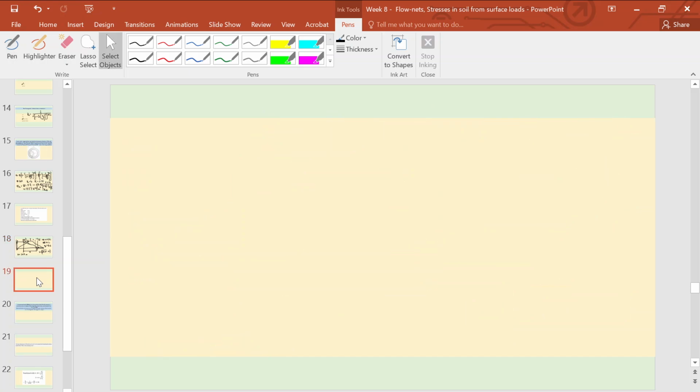So now I'll write the formula for D, which will be equal to 0.3 L, the first part on the left side upstream, plus the horizontal part having the freeboard, multiplied by the slope. Now comes the crest part. What is the crest value? 6.